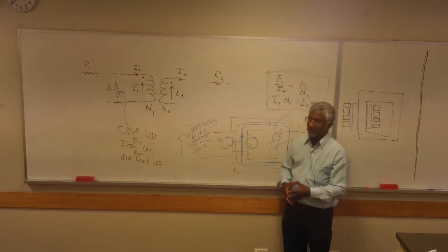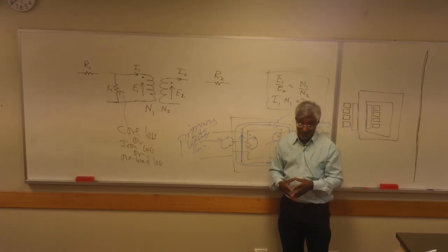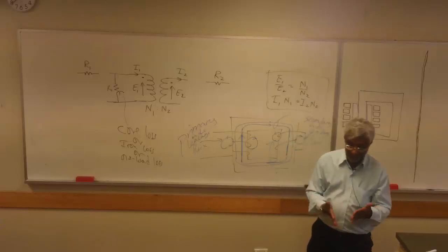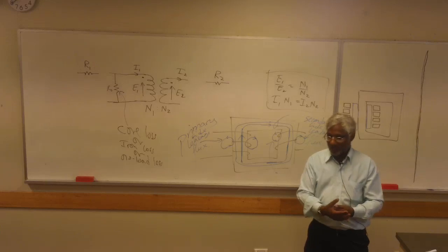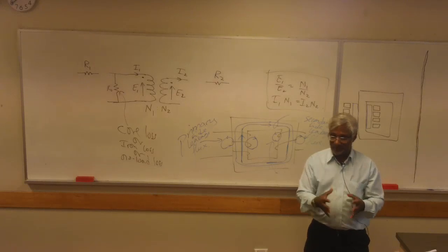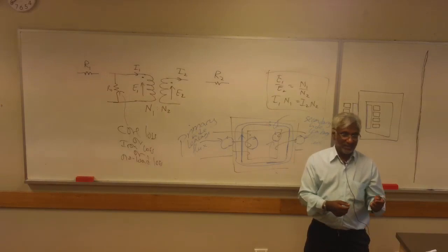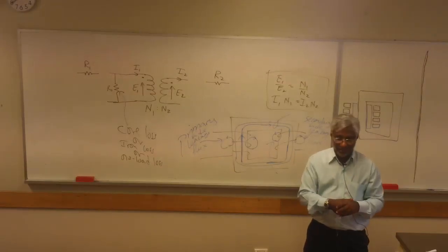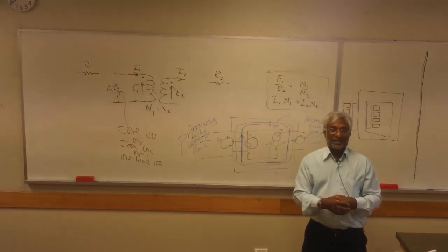We'll represent that by an inductance. And I did say last time that there's no magic about an inductance. It's defined. An inductance is the constant of proportionality between the amount of flux and current. So anything that creates flux, when you push a current through it, has inductance, and the amount of flux per ampere is what inductance is.